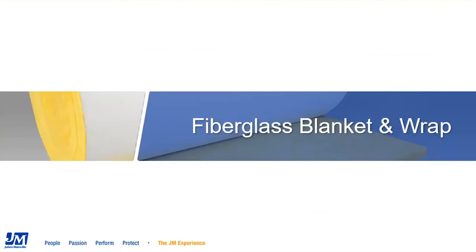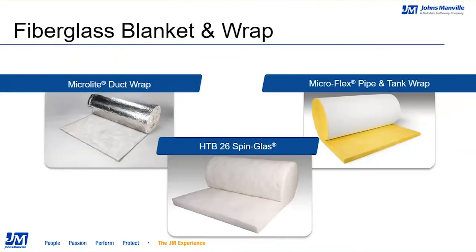Let's move on to Johns Manville's fiberglass blanket and wrap offerings. Johns Manville's blanket and wrap offering includes Microlite duct wrap that's used for wrapping HVAC ducts, Microflex pipe and tank wrap, which is a denser product used for large diameter pipe or tanks, and HTB26 spin glass that is a high temperature blanket used for industrial and marine applications.